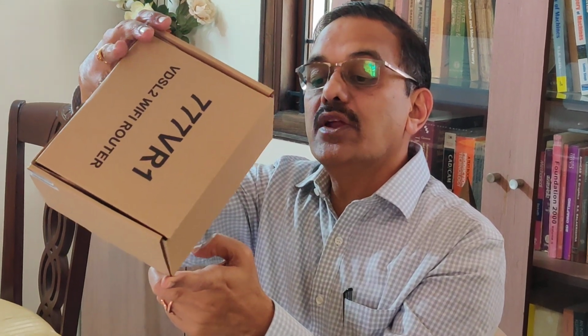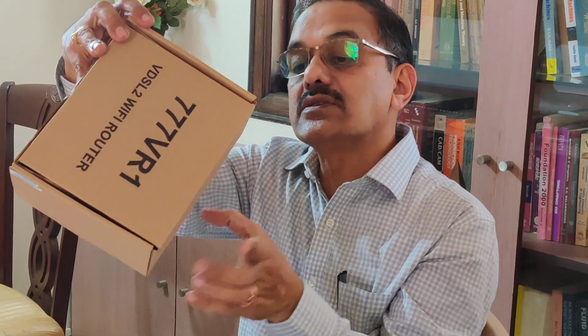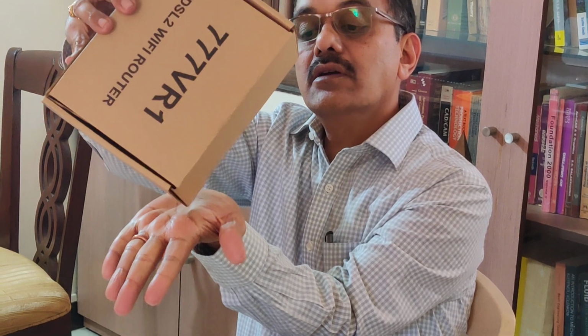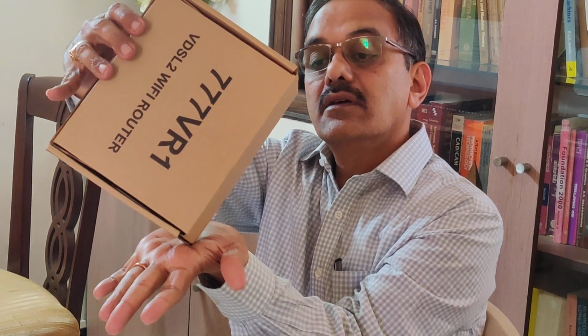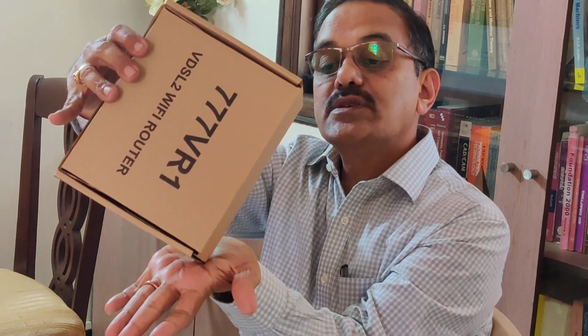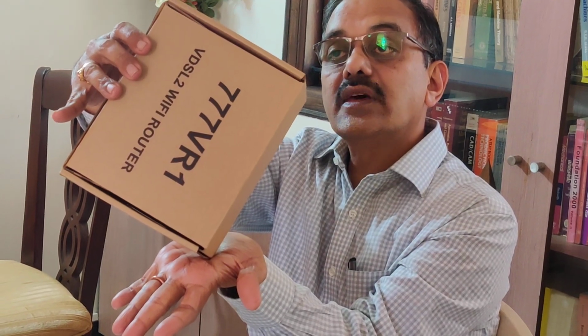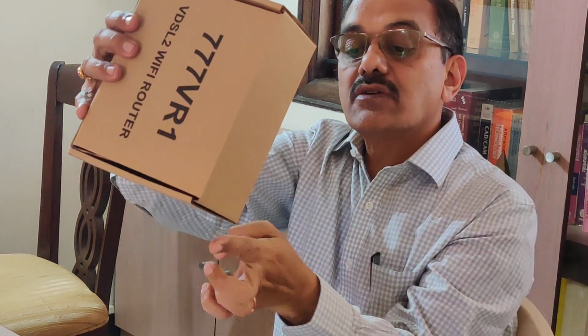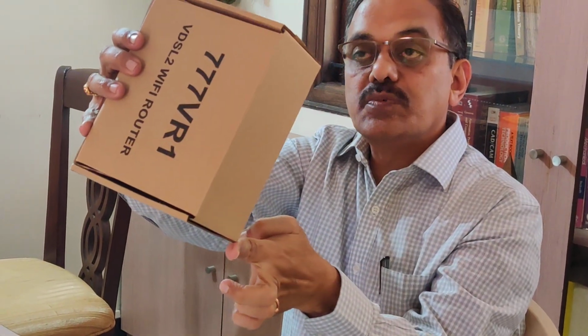So this position may be mentioned by giving any one of the angles: inclination of the base, inclination of the axis, or inclination of this longer edge. I repeat once again, it is just resting with a corner on HP, and this position can be specified by giving any one of the angles: inclination of the base with HP, inclination of the axis with HP, or inclination of this longer edge with HP.